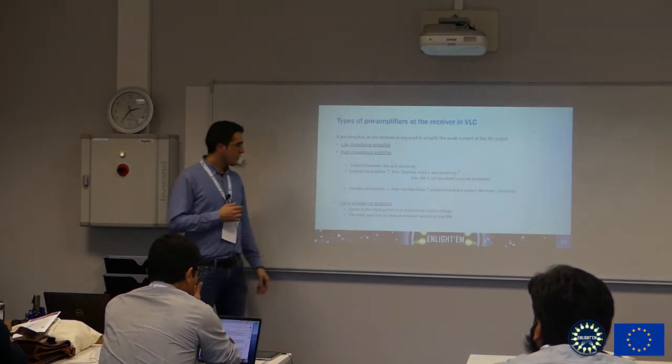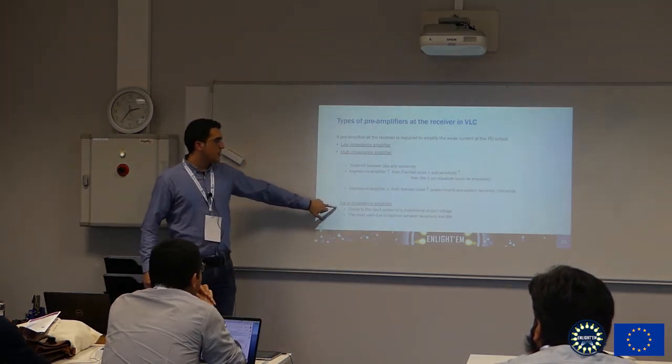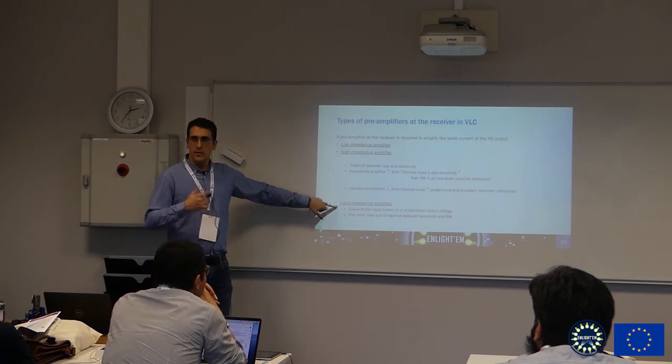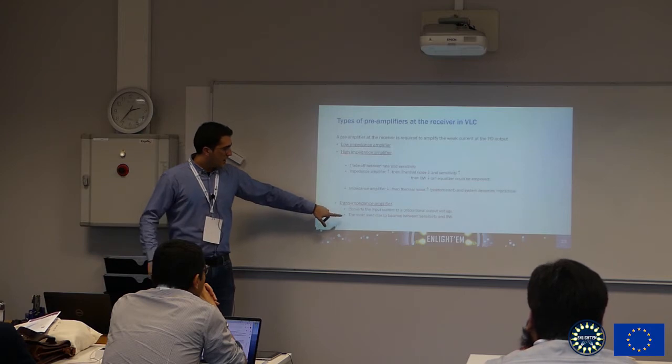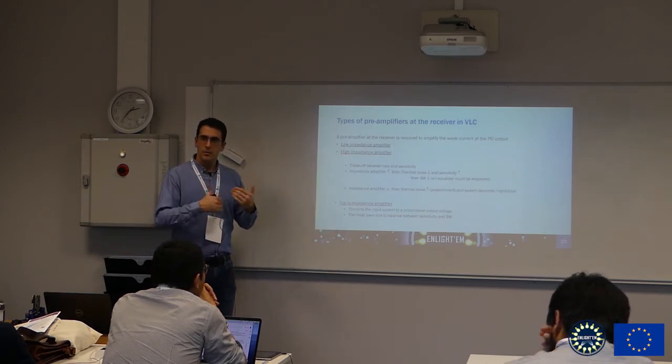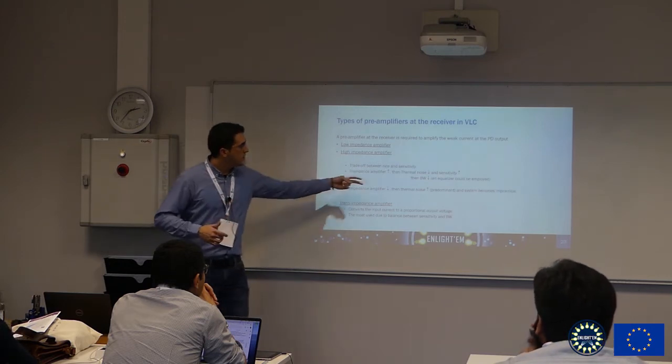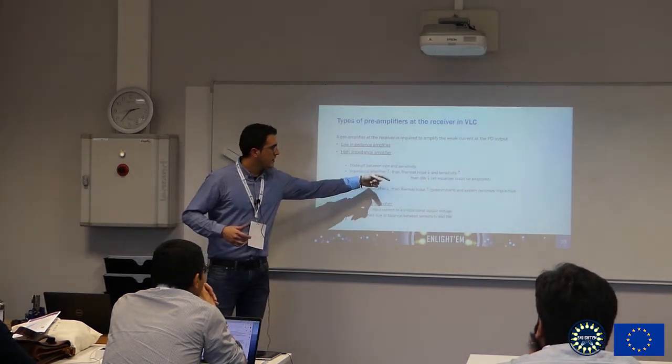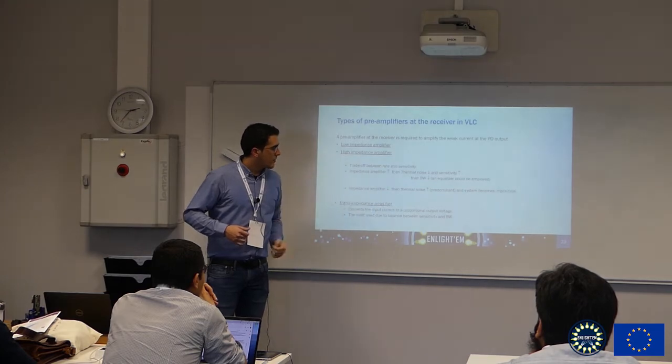And the most typical one is the transimpedance amplifier, which is converting the input current into an output voltage. They are the most used because they find a balance between these two characteristics, between the sensitivity and the bandwidth.